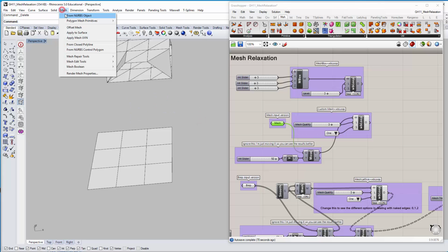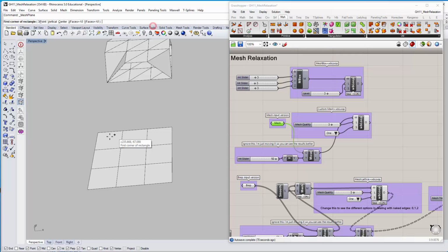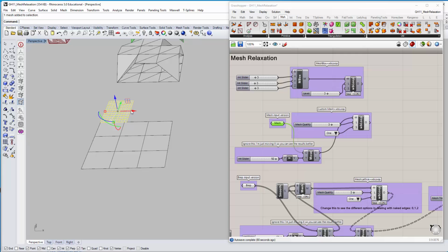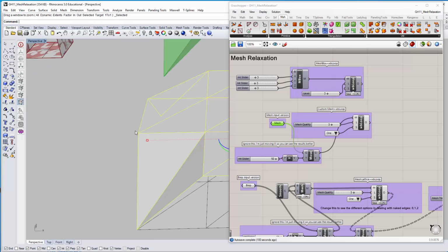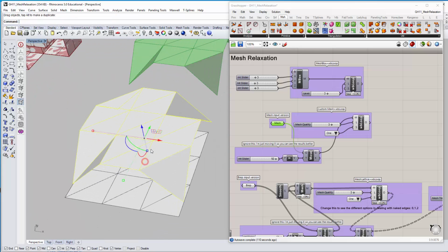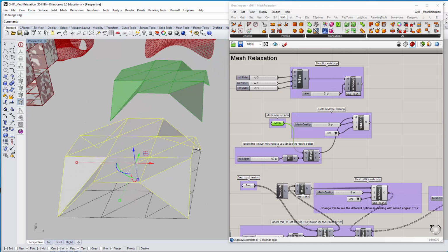Yep. And then the other one is basically the plane, which is a simple plane that has a certain amount of subdivision. Now I could draw one, and when I'm setting this, I can set the XY faces here. So if I set 3 by 3, and I can draw this, then it's almost exactly that, except you would explode this. Well, actually, this one is a mesh face with 9 mesh subdivisions. This one is drawn one by one just to show the process of getting to this. But this is essentially a mesh grouping